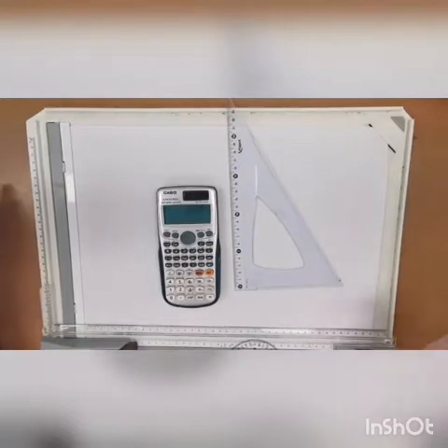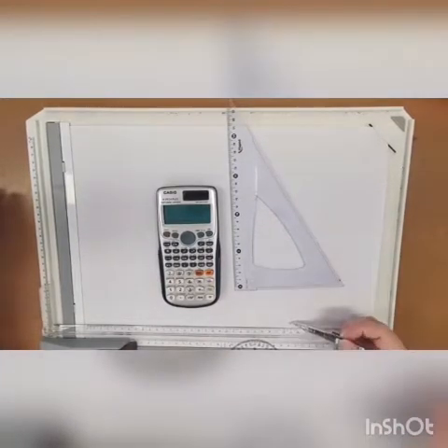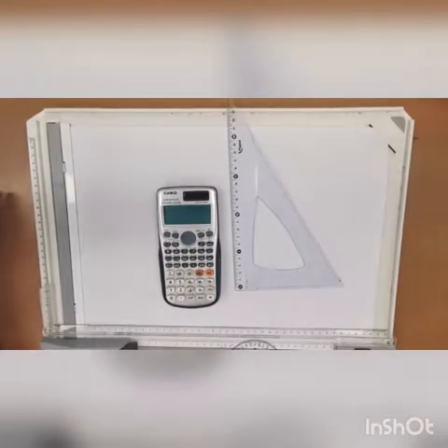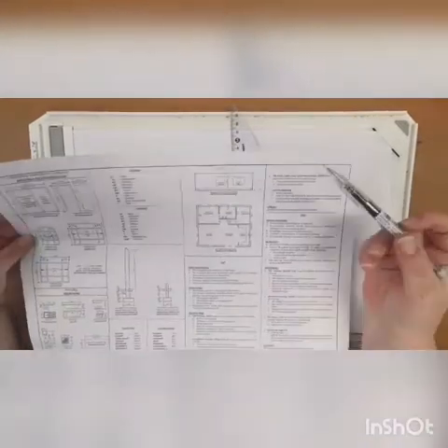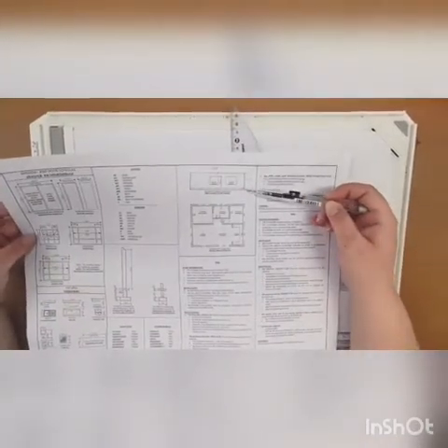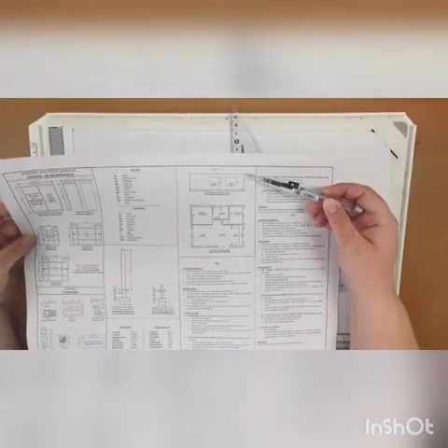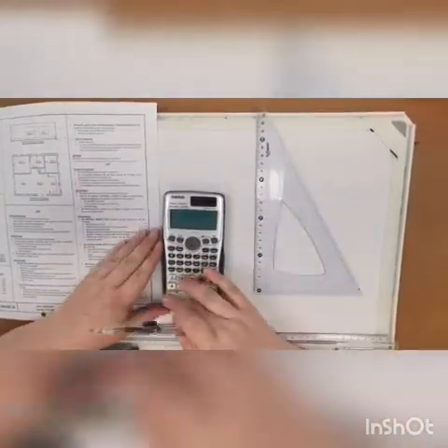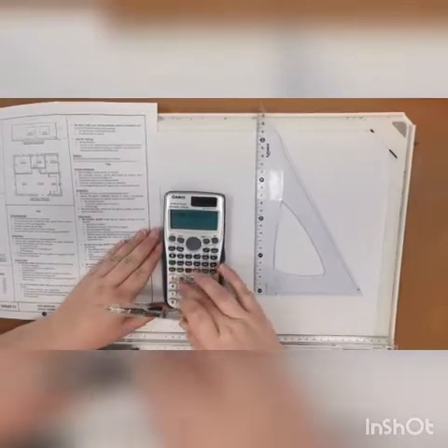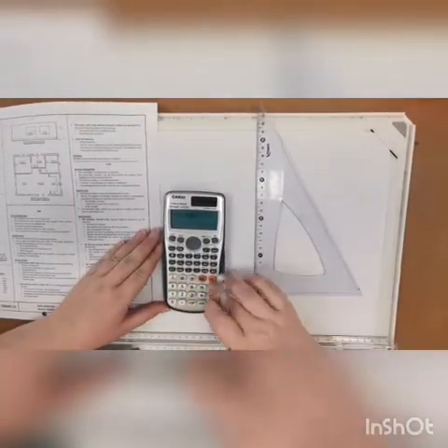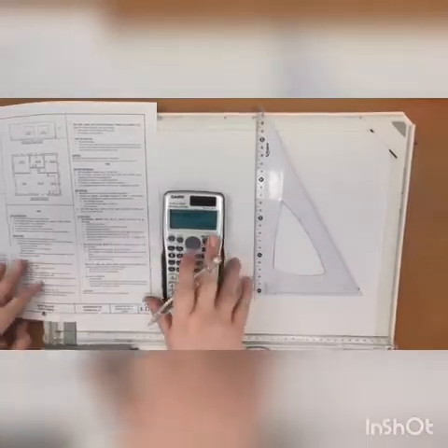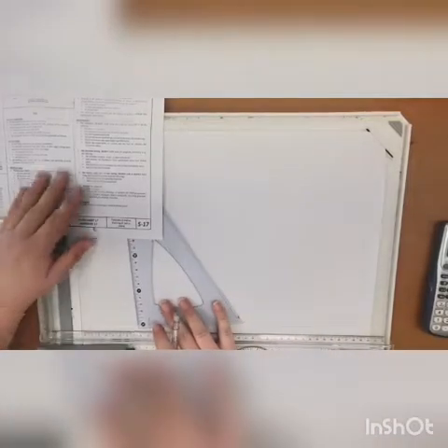It's 2761 plus 170, because if we look over here, I have 170 from the ground line to the finished floor level, and then 2761. So I should say 170 plus 2761 divided by our scale. That gives me 58.6 millimeters to the top.